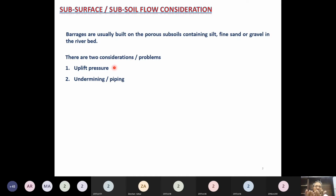So due to that uplift pressure, this will tend to push the concrete floors in an upward direction. And if the uplift pressure is more than the weight of the concrete floor, then of course these concrete floors can be lifted up and can be broken due to this uplift pressure.